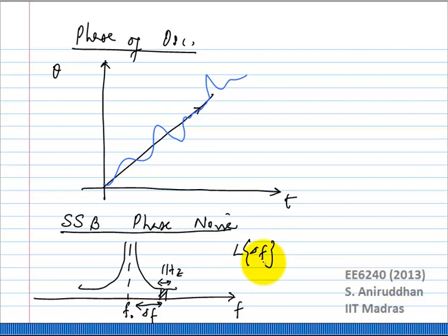And it's quite common to express the phase noise using the term L, or the more Latin or more artistic form of L, maybe something like this. But it's a lot easier for me to just use L. So L of delta f is 10 log of, so it's represented in some kind of dB terms, 10 log of the power in this 1 Hertz bandwidth at f0 plus delta f, over